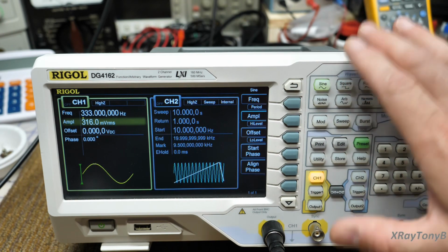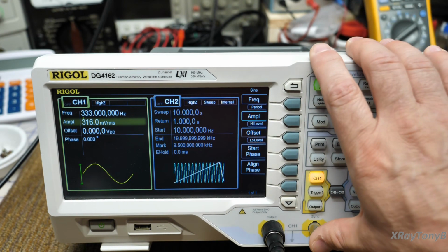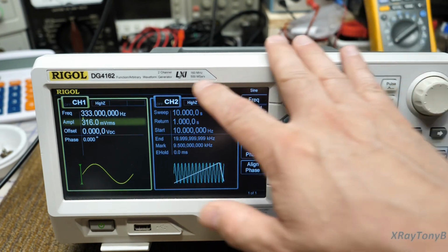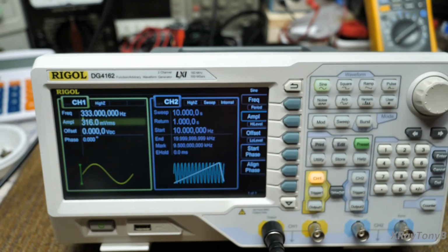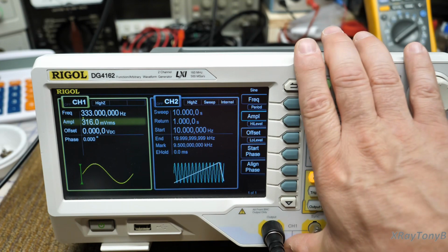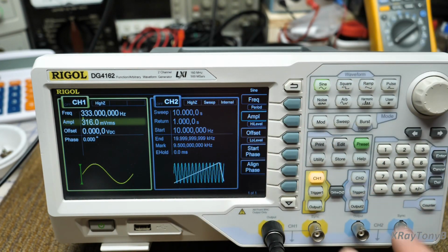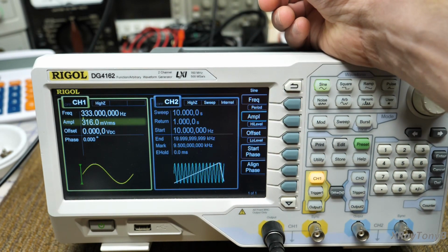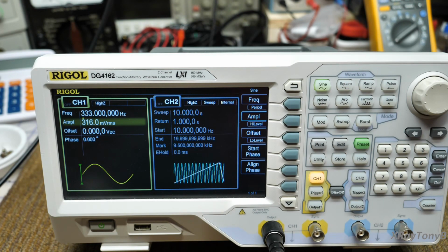Now that's one of the trade-offs. Most function generators and arbitrary waveform generators, especially the less expensive ones, do not go this high. Many of them will only go up to 10 megahertz or 20 megahertz or something like that. They will not go this high. And that's one of the reasons that they cost less money. So you can get one that looks very similar to this, does everything that this does, but it will not go up into the frequencies you need to be to do FM radio. So that's one thing you have to remember. So this one can do it, so we're going to go ahead.